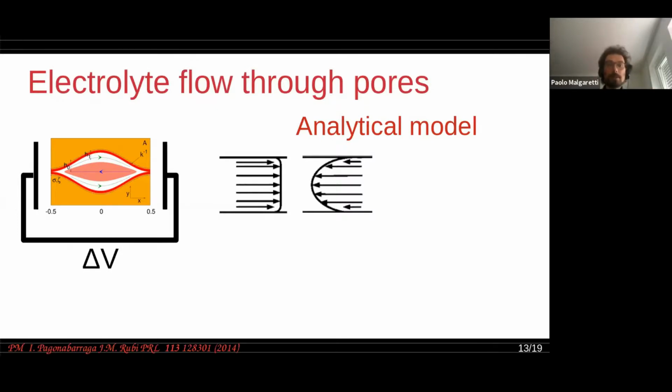So what the system can do is to set up local pressure gradients to compensate for this flow that will be different in the wide section of the pipe and in the small section of the pipe. And then in practice, everywhere you have to sum up this propagating plug flow, this is called plug flow, and this back propagating Poiseuille flow, whose shape is a parabola. Now, if you sum up these two functions, you can have different kinds of functions. And here I'm plotting them for you.